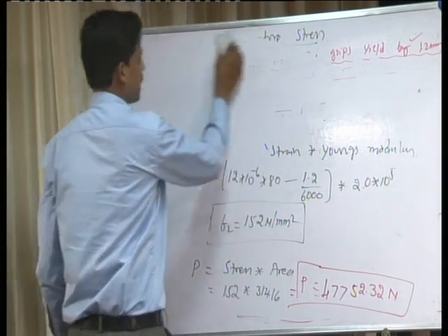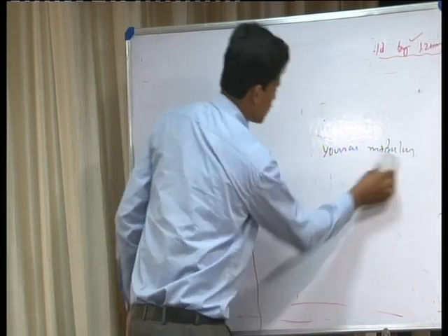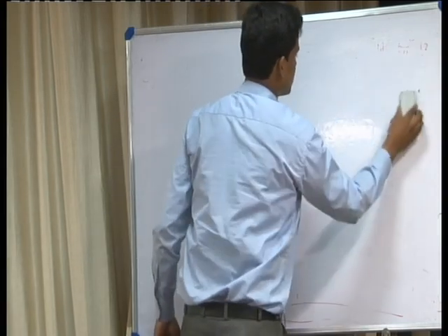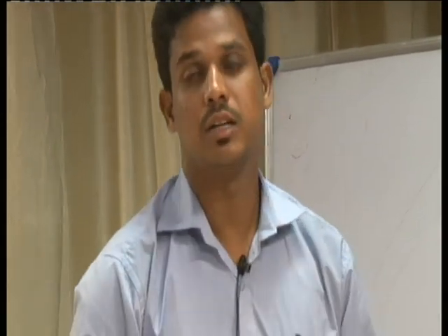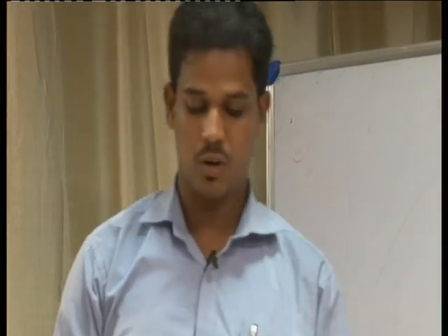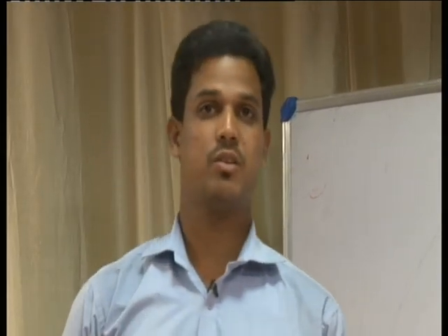Today in this class we have learnt how to analyze composite sections: how much stress is developed and shared in the section, what strains are developed, and what load is shared by the section. We have also studied temperature effects and the temperature stresses developed in the section.